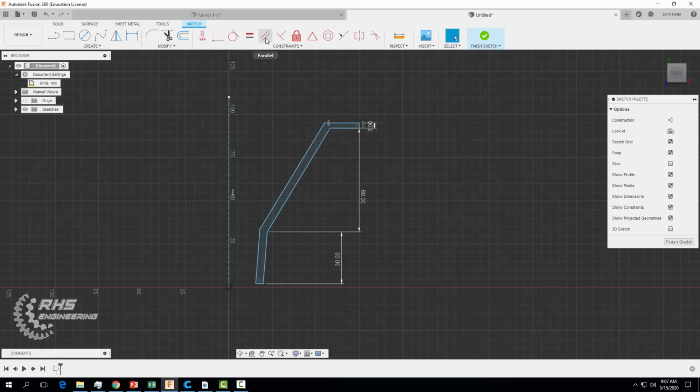And I want to add now some geometric constraints. I want to make sure these guys are parallel. So I'm going to click here and here, make sure that's parallel, make sure that one's parallel. Oh, and we get an error. So these are already parallel. We already added this parallel constraint when we drew it, so you may not have had that case. You may need to make these parallel. Now I'm going to hit escape to take it out of my parallel constraint.